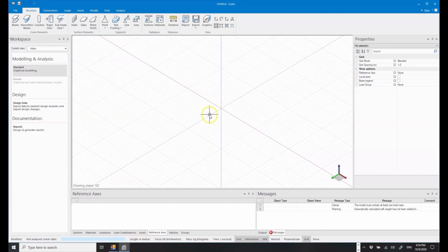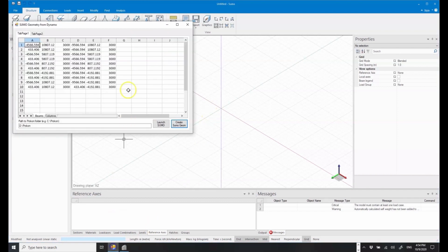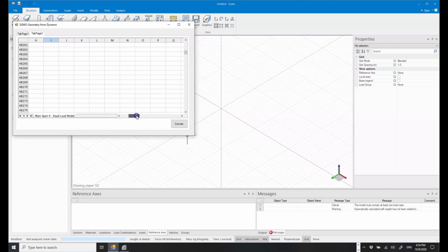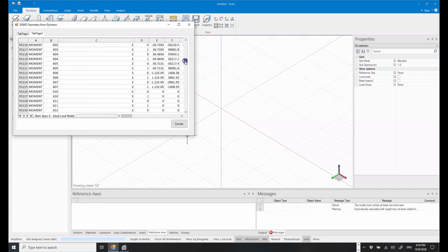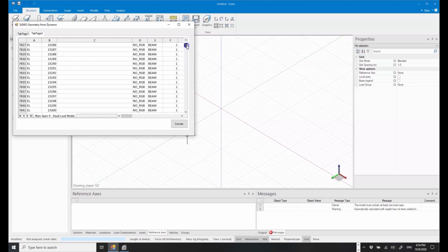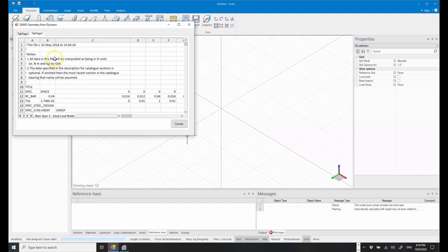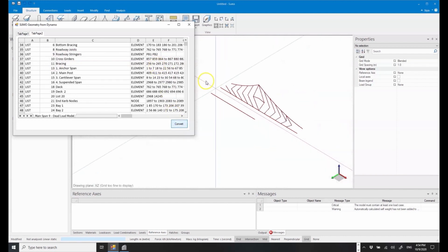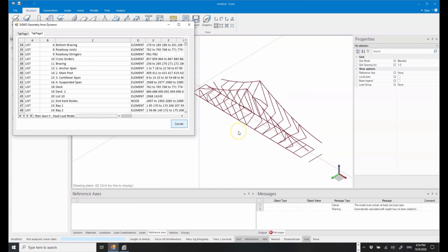Now, if we wanted to create a much more complex model, we can do that too. And you'll notice that I'm able to use Sumo and my automation script on the side all together in the same session. Now this one here is a lot more complex. This was actually data that was exported from another program and we wanted to replicate those results in Sumo to see what that looks like. And here you'll see we've got a whole bunch of different nodes that indicate force, displacement, the actual connection of elements, and the program interprets these lines and looks for certain elements and then automatically converts that into a model. So without delay, I'm going to hit convert and you'll see what happens in the back end.